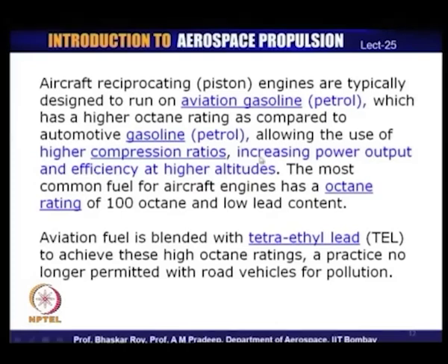Now, this kind of fuel is typified by what is known as high octane value. An octane rating is given in terms of 100, and aircraft fuels are often of 100 octane, and they often have a small amount of lead content. This lead is tetraethyl lead, which is added to a basic fuel, often some variety of petrol, to provide a high octane rating.